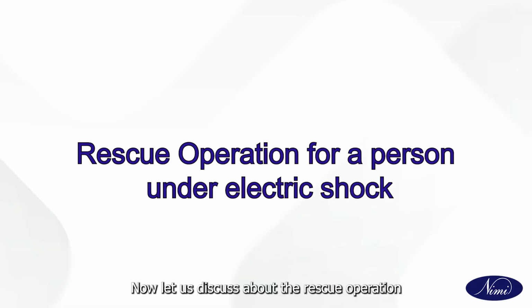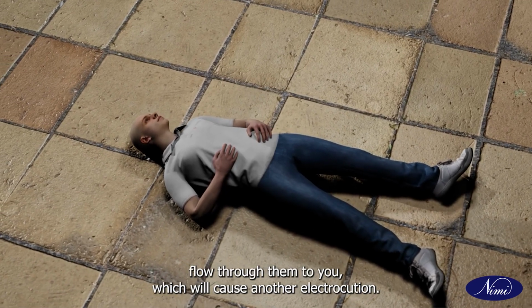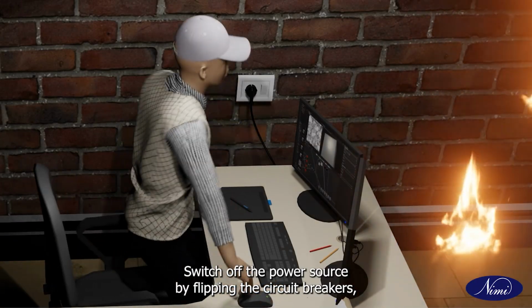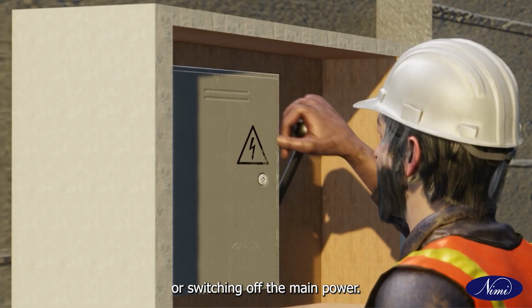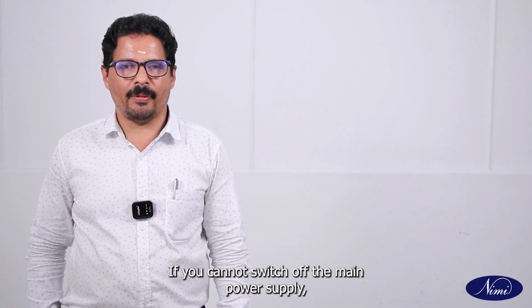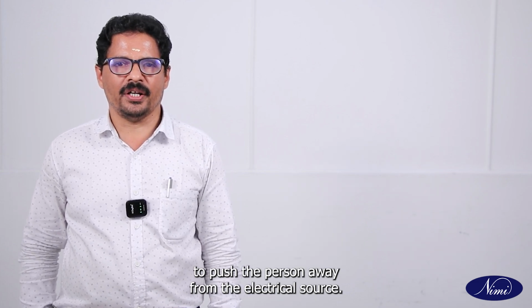Now let us discuss the rescue operation on a person who is under electrical shock. Do not touch the person who is in electrical contact directly. Otherwise, the current will flow through them to you, which will cause another electrocution. Switch off the power source by flipping the circuit breakers, removing the appliance plugs, or switching off the main power. If you cannot switch off the main power supply, use non-conductive materials like rubber gloves or plastic chairs to push the person away from the electrical source.